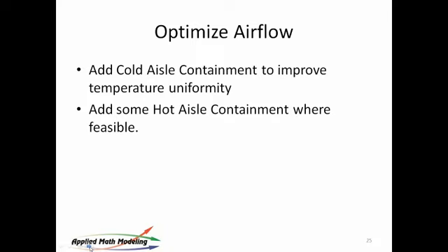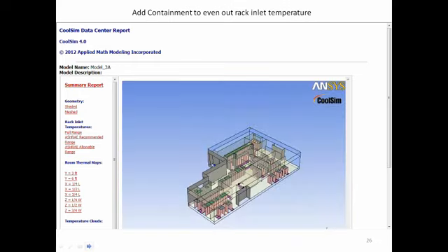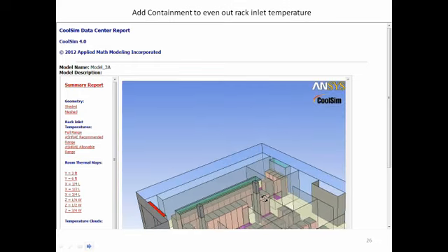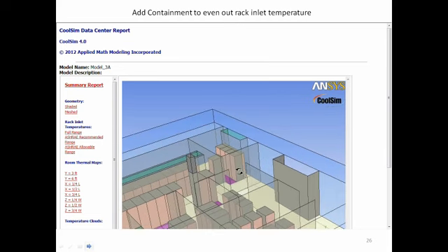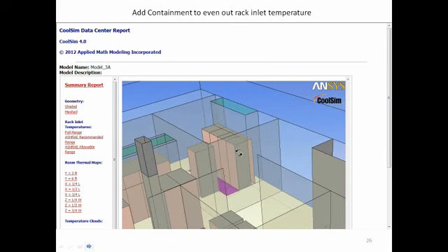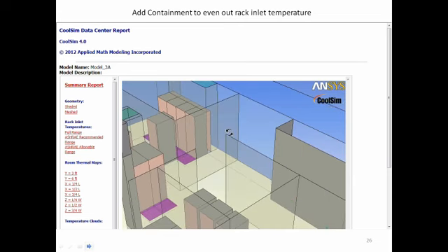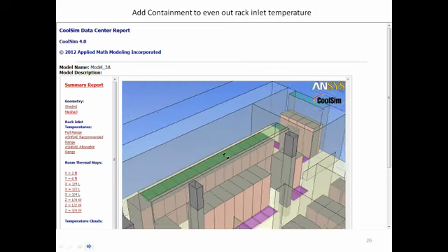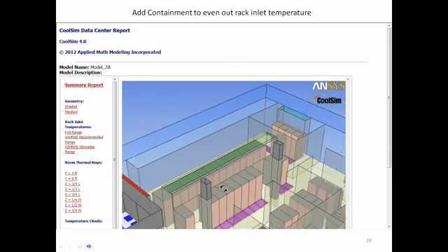So in the next model, we use a little bit of cold aisle and a little bit of hot aisle, a little bit of both. Fortunately, in this room we have a ceiling plenum, and that helps with respect to hot aisle in a few key areas. For example, here's a set of equipment over here up against the wall, and it's got ceiling plenum return grills up above. Very nice place to put some curtains. Another natural hot aisle in this room, that's a hot aisle. Another natural hot aisle is right here.